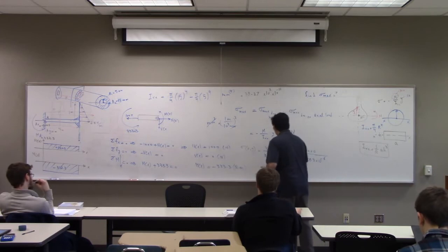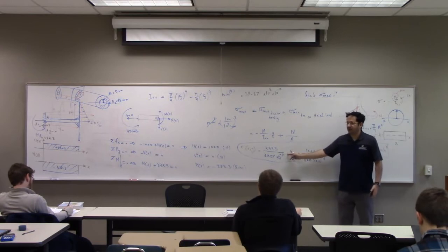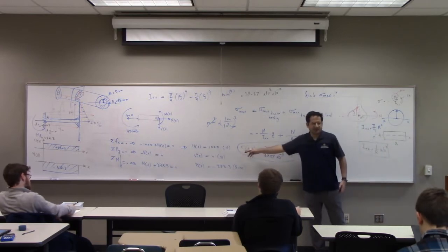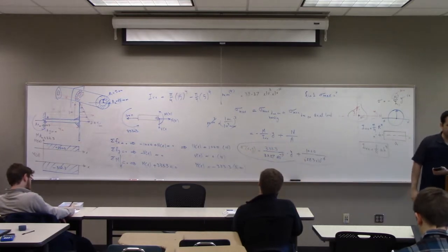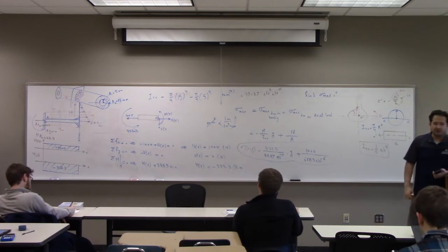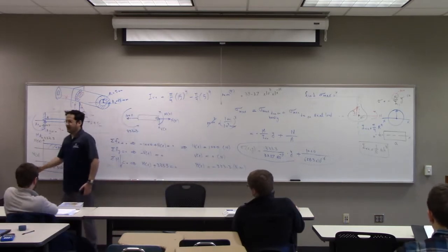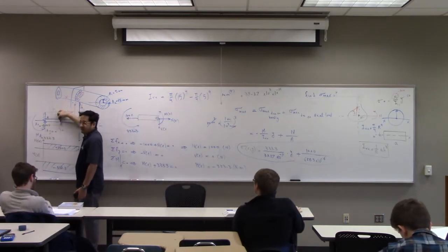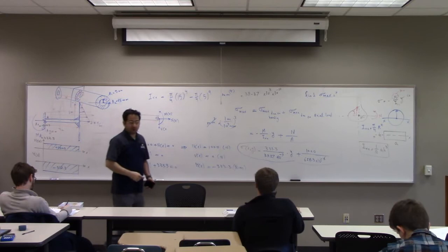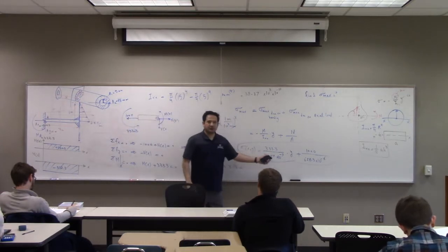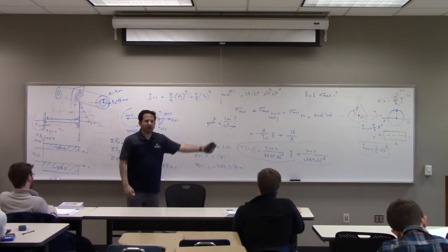That's it. So you see your stress field, it's a function of y, but not a function of x. I may give an example in the test where a stress field is a function of x too. How can it be a function of x? When your moment is a function of x. You see the moment is constant here. Now if you had a cross load like that, or a bending moment here, then the moment will depend on the x. Right? So now the question, optimization, find the maximum of that. Where is the maximum for that? Find the y location of the maximum.